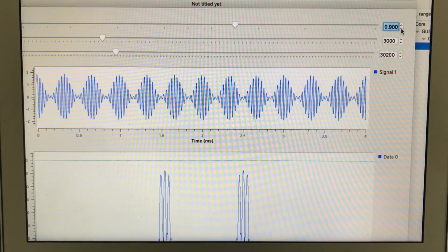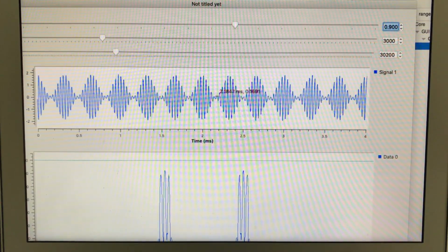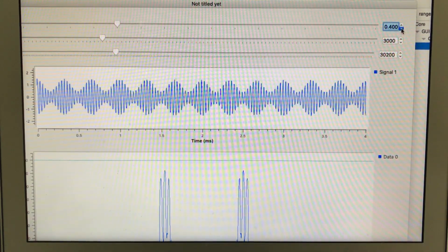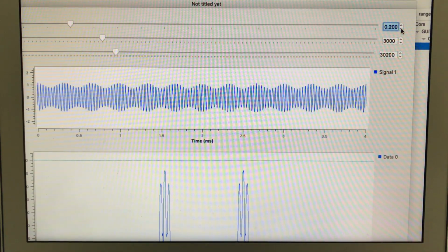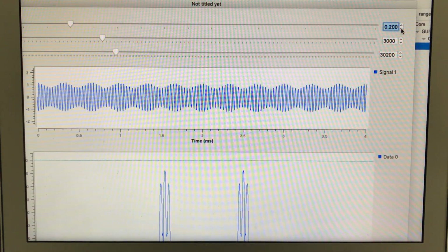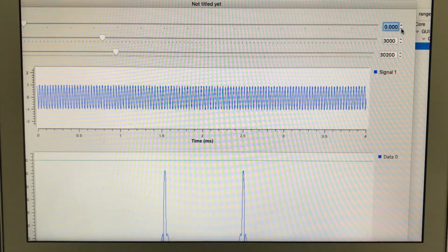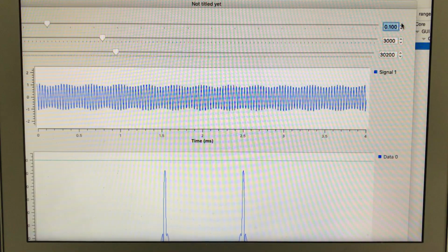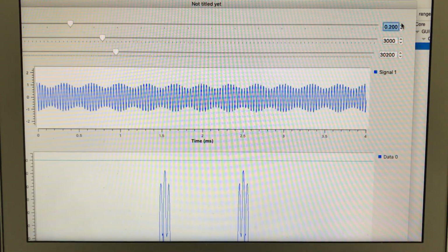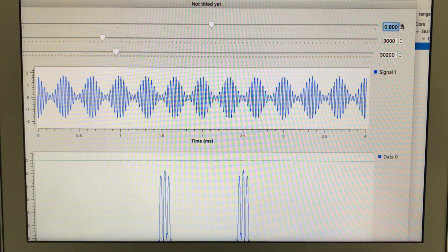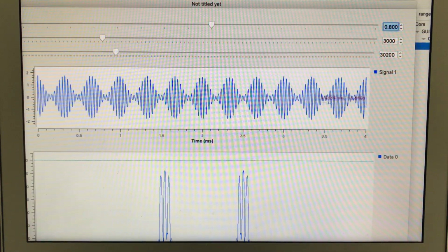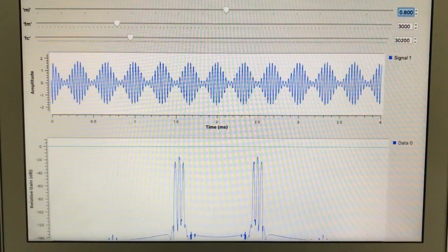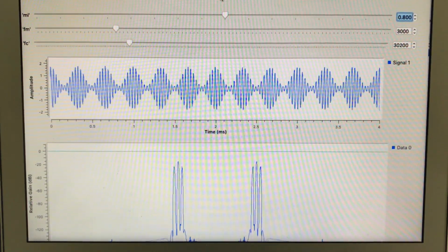Now let's go to 90%. As you can see, in the middle this is no more 0. And let me bring it down completely. So this is an under-modulated signal. Once you don't have that modulation factor, you will just get your carrier signal back. That's it, it's that simple. Then when you apply modulation by changing the modulation index, here we go. Modulation is happening and you start seeing the envelope associated with your flow graph, the envelope that should be there for your AM signal.